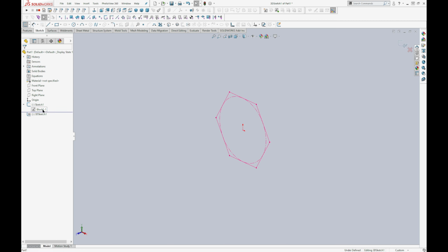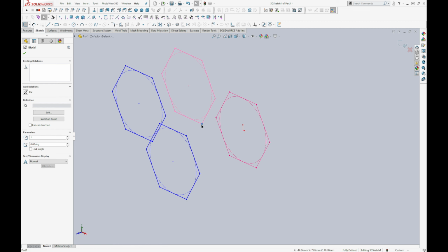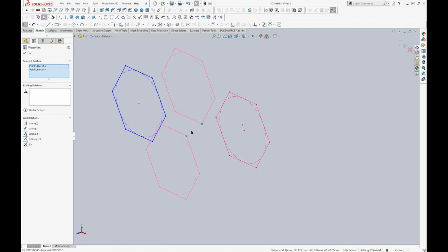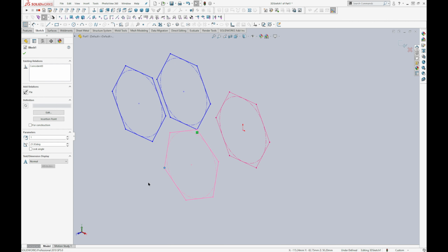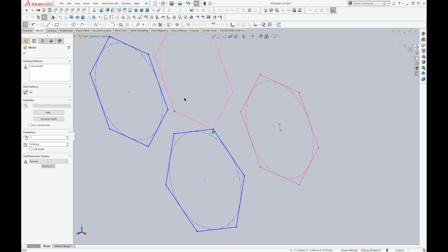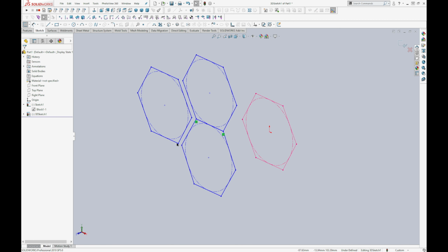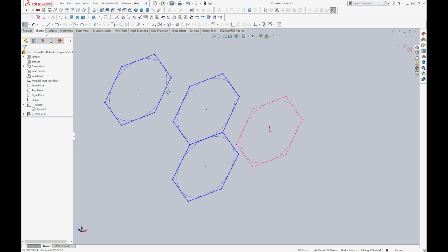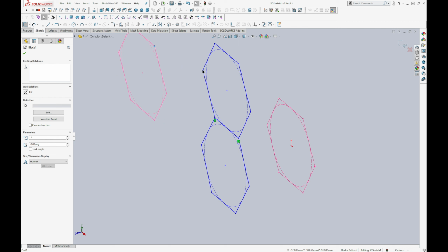So here I'm selecting a 3D sketch and I'm actually copying the block with Ctrl+C, Ctrl+V. And now I can paste it as many times as I like. So now I'm going to connect the edges or the corners of the polygons together. You see, because of the blocks, it acts like an assembly. So you can connect the endpoints, and form basically the shape of the cell.